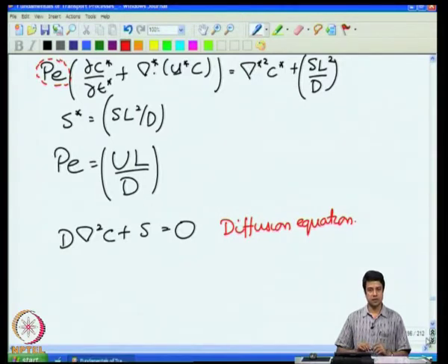We will see that in our next section on high Peclet number flows. We will use techniques similar to the similarity solutions that we have been using successfully all this while in that case. Okay. For now, let us focus on the diffusion equation, where we set the Peclet number to 0 so that the convective terms are no longer important.